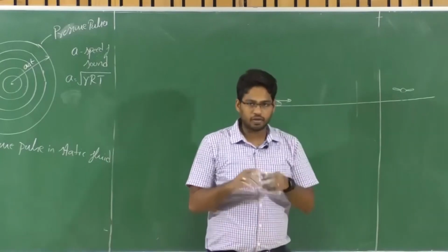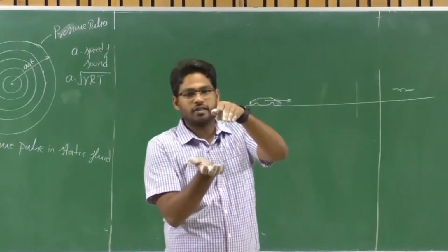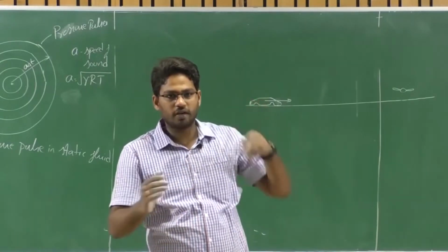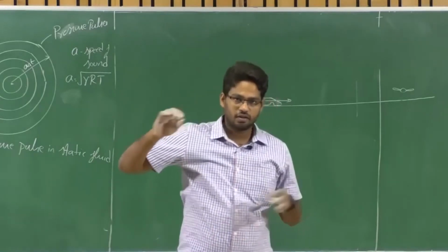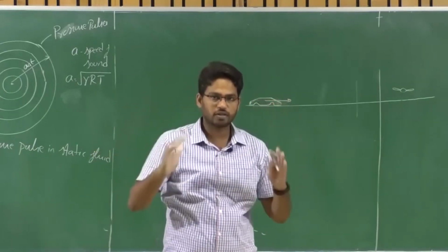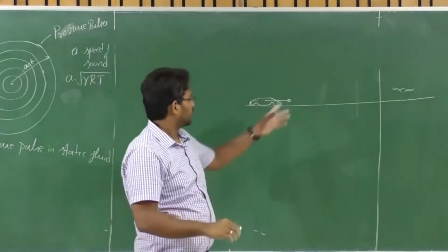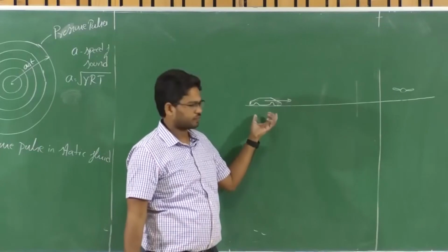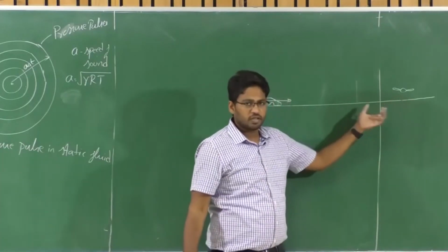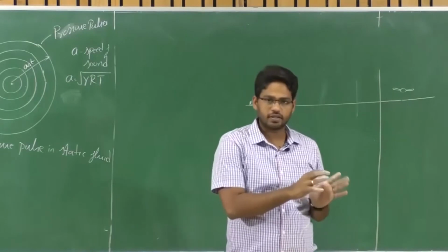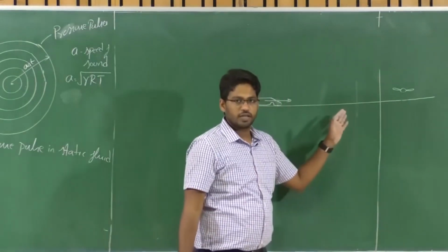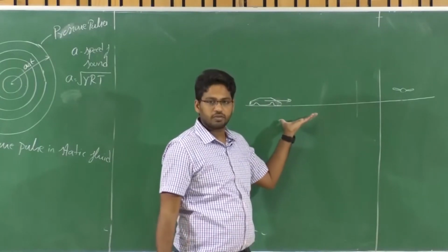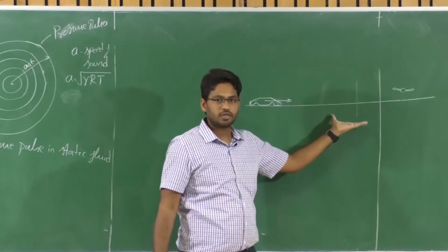And the flow particles ahead of the vehicle will try to adjust accordingly. So it will try to figure out where the disturbance is minimal, right? And the fluid particles in the form of these streamlines can bend across this vehicle so that they can smoothly flow over this particular body. Fine. So this is true as long as the disturbance is traveling forward. Now, as I told you, this disturbance travels at the velocity of sound, right?